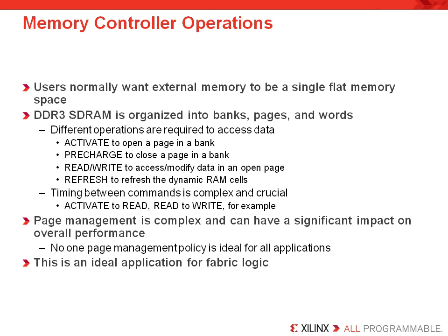But the key thing here is to understand that the timing between the commands is complex and crucial. And this is one of the reasons that it's so important that the memory controller be built properly, because no one page management policy is going to be ideal for all applications.